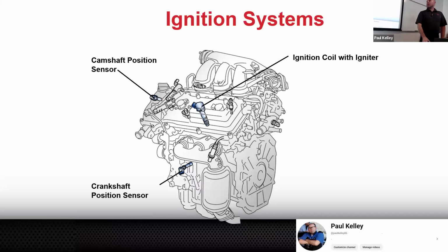My suspicion is you have an open circuit on the primary wires between the coil and the ECM. So start looking those over. And then if you'll recall, I got a picture of a wire chewed right at the coil. So if you got a misfire, we're going to pop the hood, and we might check codes first, or sometimes I'll visually inspect it, right? But just understand, if the small wires going into the coils on coil on plug get chewed, that coil will not fire. Make sense? So in her case, when she showed the damage of the wire at the connector, it was like, hey, you got to buy a new connector with the little pigtail harness, crimp those on, plug it in.